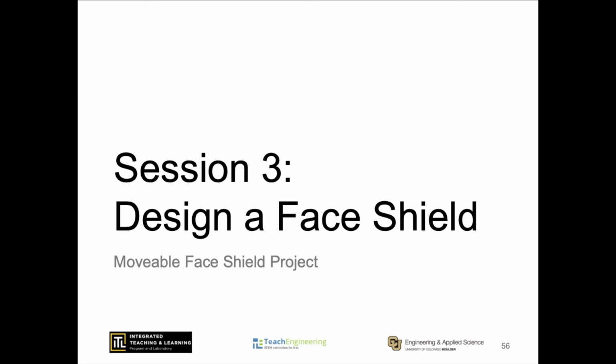Session 3, Design a Face Shield. Today we will be designing a headband for a COVID face visor. We will use various features of Onshape to help us get a useful headband design, which can be 3D printed for actual use.